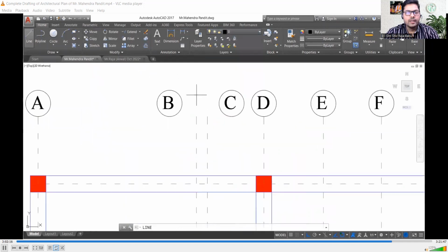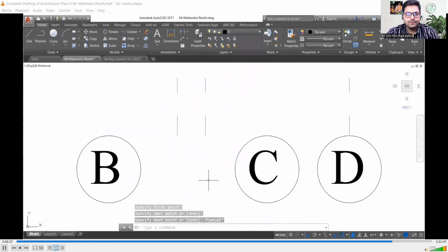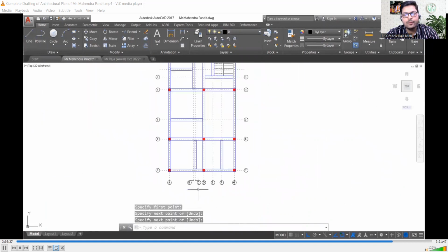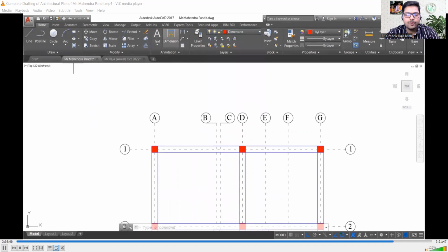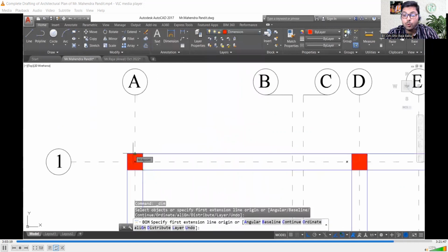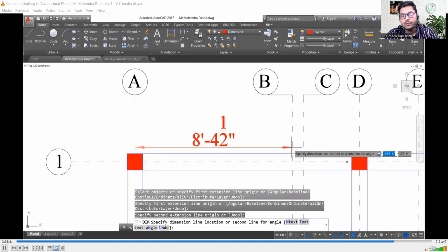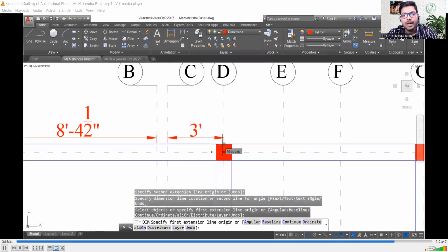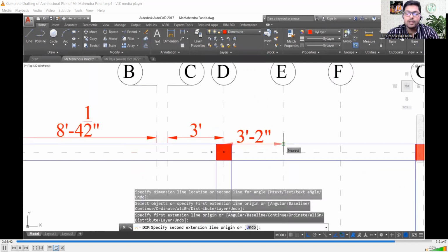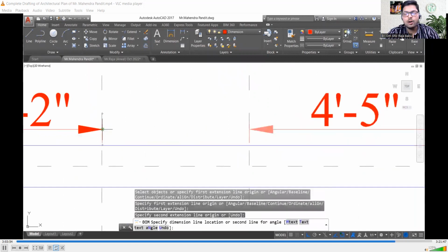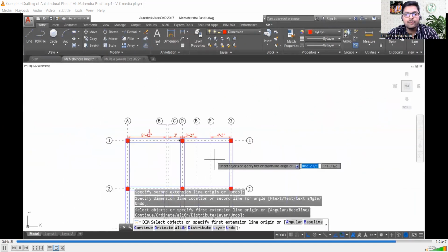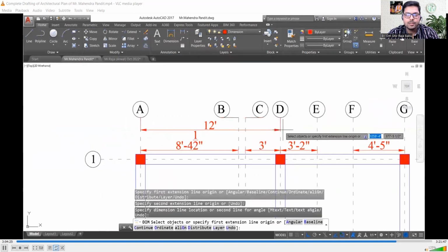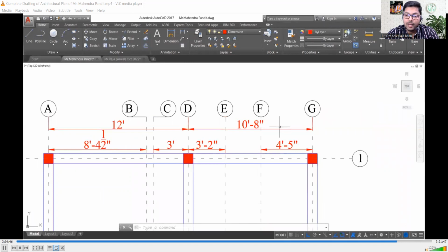There is nothing wrong with any of them, and you can see what I have to do over here. I need to mark the exact lines over here. You'll find that these center lines are too close, and this happens when we do not follow the symmetry option. To mark such center lines, what is the best thing that we can do? We need to mark these center lines from the columns, because the column markings are already given in the tie beam layout, right?